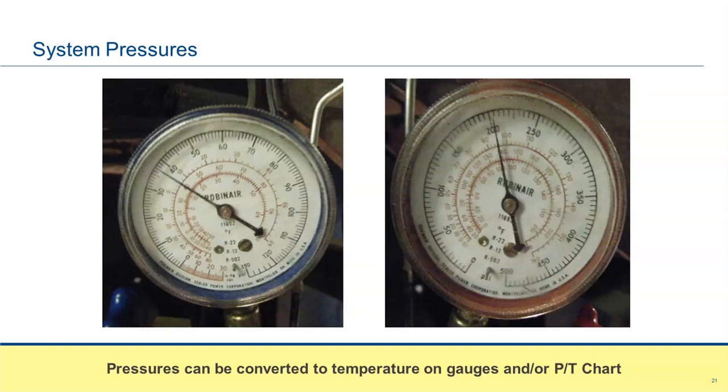You can walk into a walk-in cooler, if you're in refrigeration, that box might be always 30. I'm just going to throw a number out here, or 25, or whatever that looks like, whether it's medium or low temp, okay? But the refrigerant pressures might be different depending on what refrigerant they're using. For you residential guys and gals, you can have two houses side by side, same application, same load on the houses, same amount of people.